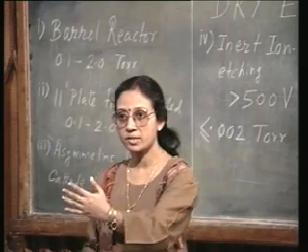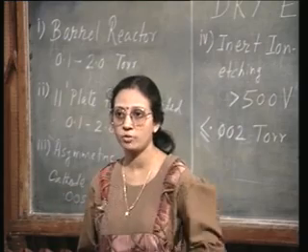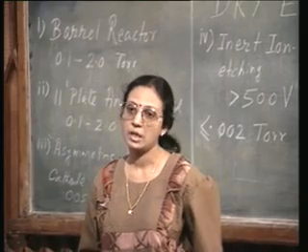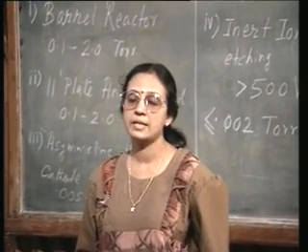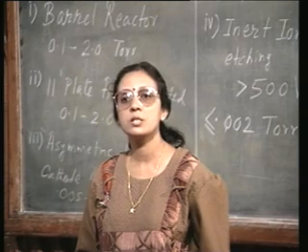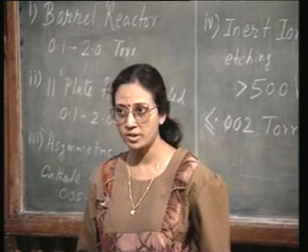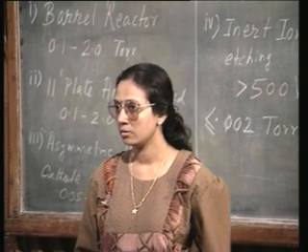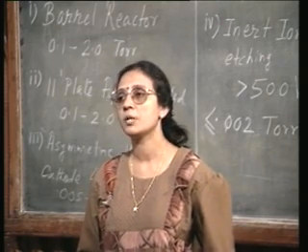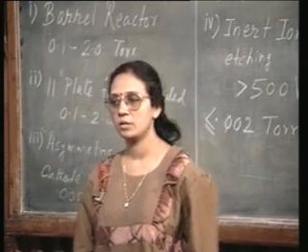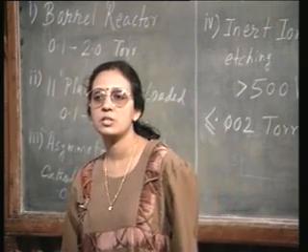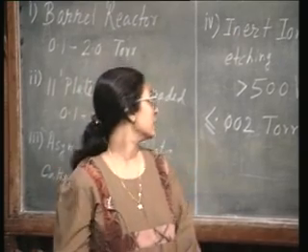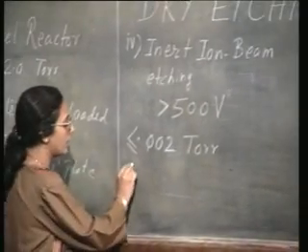Only those surfaces which are exposed to this onslaught of ion beam is going to get etched, side walls are going to be completely protected. But this high energy ion beam is not going to distinguish between the different types of surfaces. So, selectivity is the casualty, right. You have very good anisotropy, but you have very poor selectivity. To improve the selectivity to a certain extent, there is a variation of this which is reactive ion beam etching.